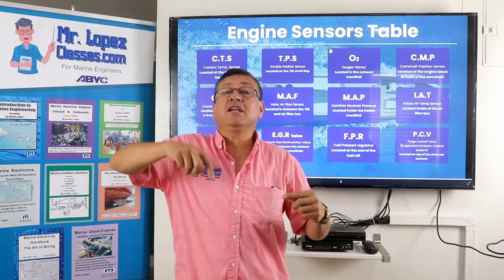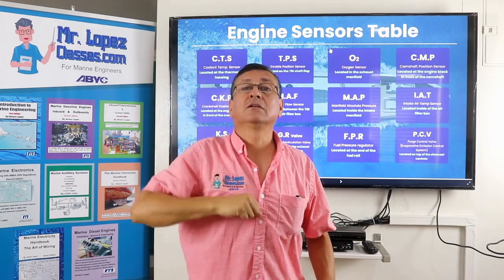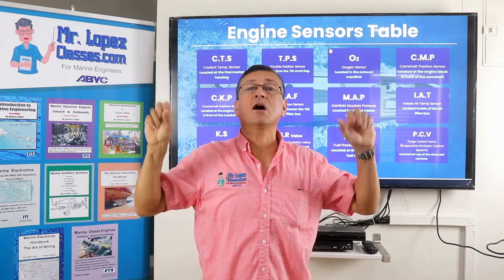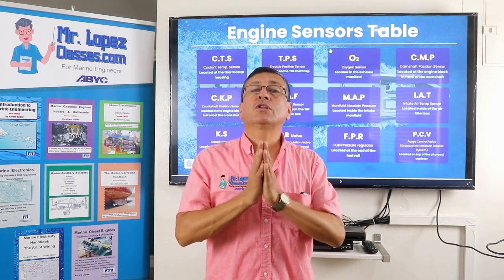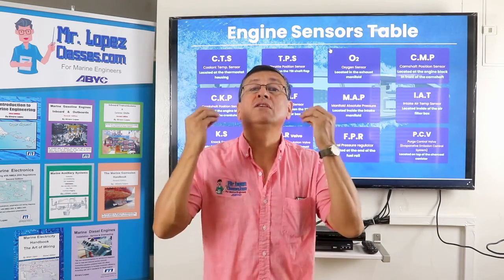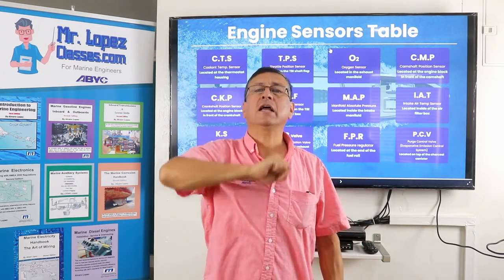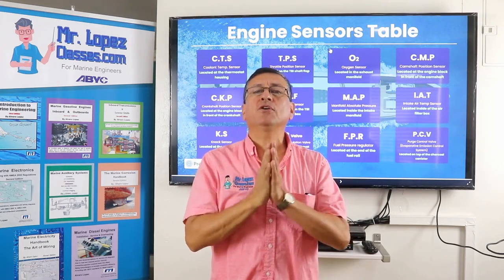Finally, at the end of the circuit, that element reads a different voltage or different ohms, and the computer immediately starts the alarm. Before you try to clear a code, you need to solve the problem. If the problem is not solved, the code starts again. Alright? Be careful with that. This is the most important part.